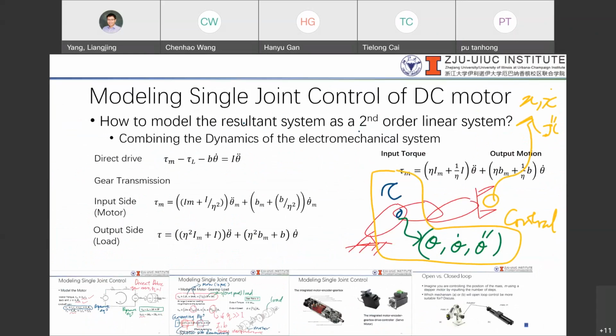If we look at a gear ratio that is very high, much larger than 1, your motor side will actually be the dominating one. So external force is not going to influence too much. And so most likely when you send a certain command to ask a motor to move, whatever displacement is going to be done more accurately. The external disturbance will have less influence on it.